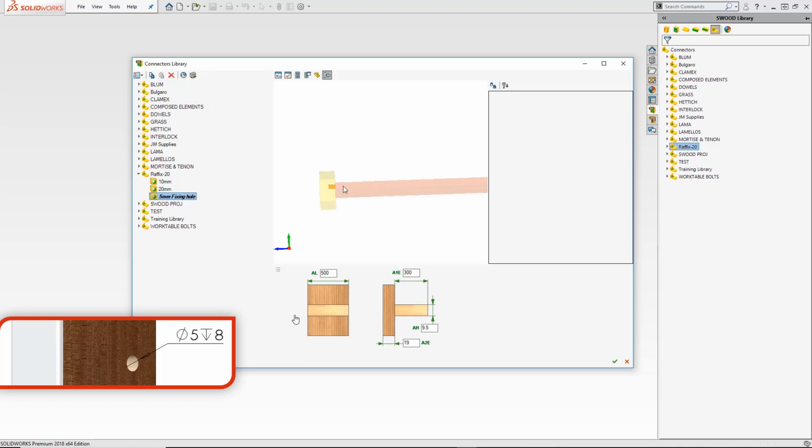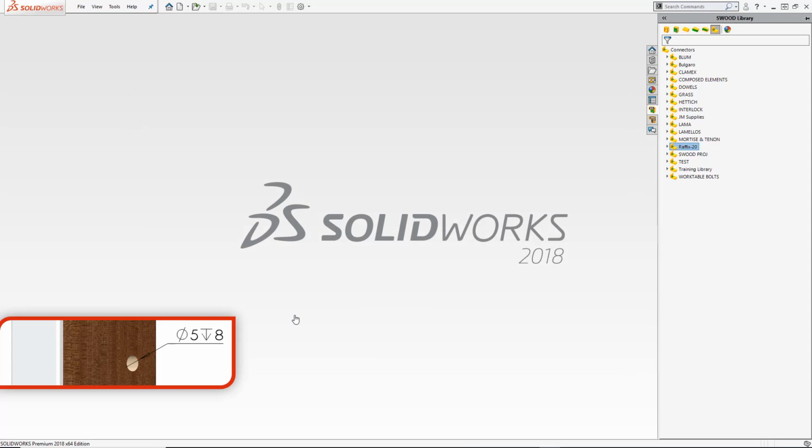So just looking in test mode here now, what you should see is that the hole, this kind of yellow body, will always be 9.5 mil from the bottom of the shelf. So when it's 20, you can see, and see when it's 30, you can see it's just a third of the way up. When it's 9.5, you can see it's exactly on the top surface. So that's a little test there where you can try out different measurements and just see if the hole is moving as required.